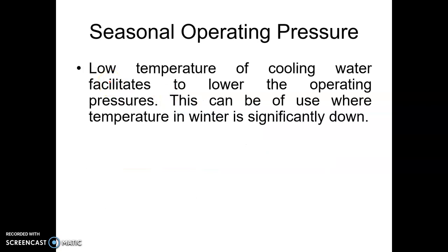So we know that changes in pressure impact the separation. If I decrease the pressure, my VLE diagram will make it easy separation. So VLE would be favoring the separation. So the lesser the pressure, the easier the separation. The more the pressure, the more difficult the separation. Now, if I decrease the pressure, the boiling points will also decrease. Now, decreasing boiling point means what? My reboiler boiling point also decreases, so reboiler temperature decreases, but at the same time, condenser temperature also decreases.